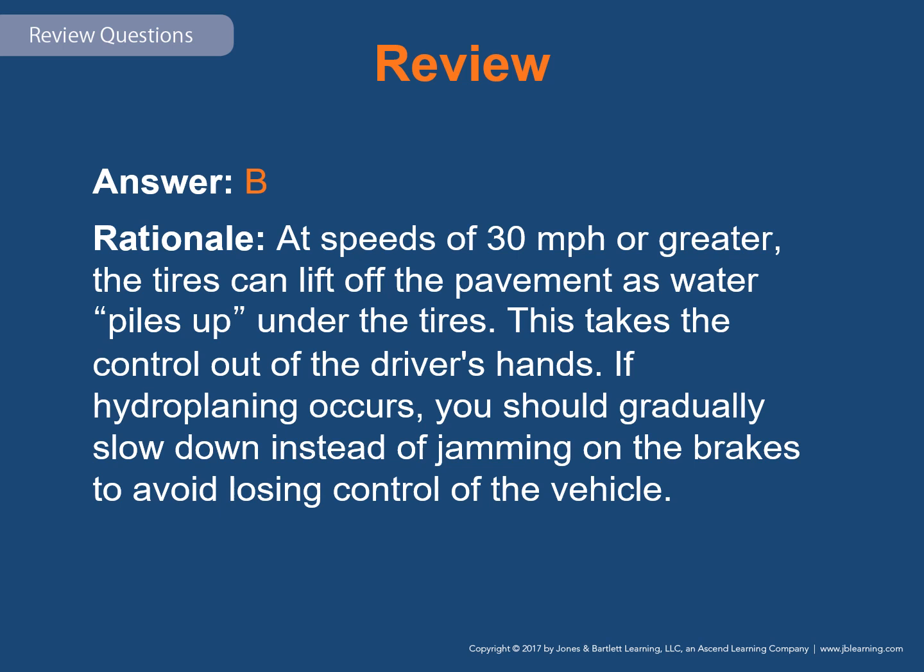This takes control out of the driver's hands. If hydroplaning occurs, you should gradually slow down instead of jamming on the brakes to avoid losing control of your vehicle. Just take your foot off the gas immediately and almost let the vehicle steer itself through the hydroplane. Brake very gently if you have to brake at all.